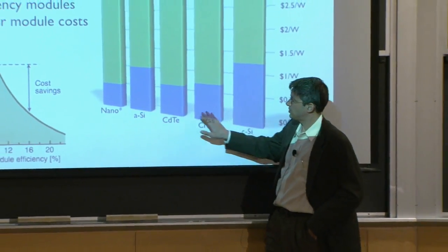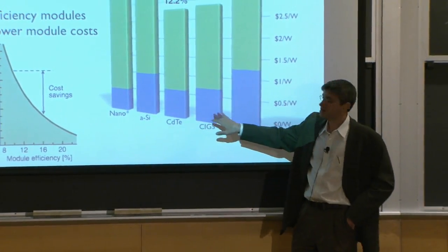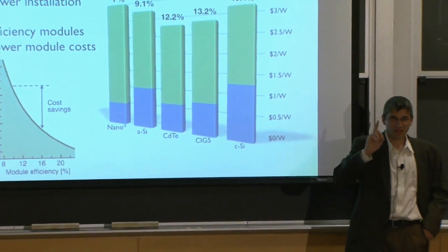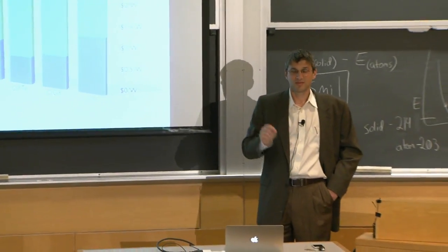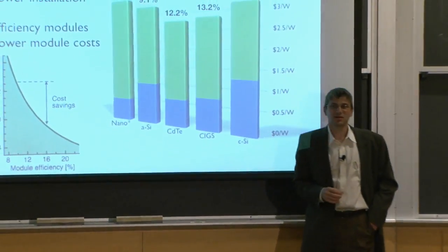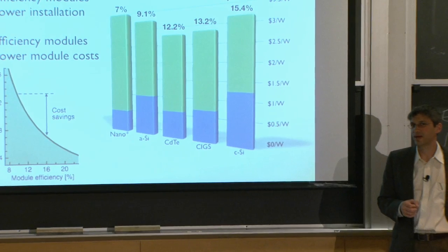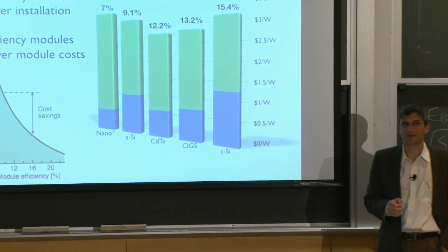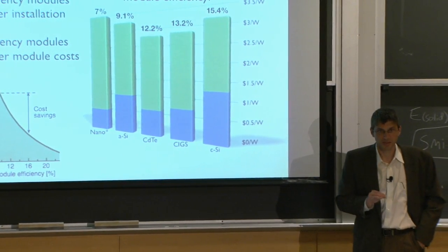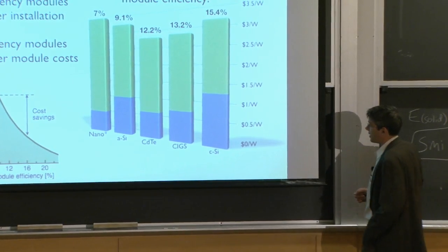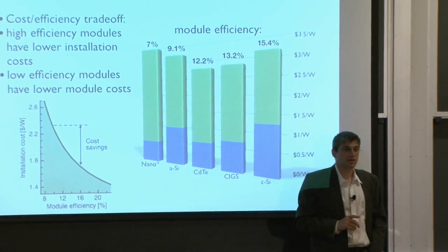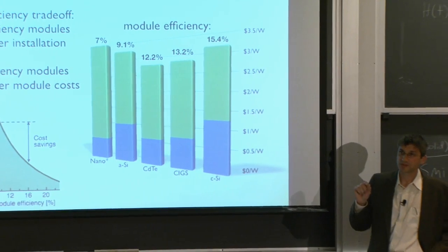So these are all thin film. These are all thin film. This is thick film. Now, what can you compute because of this class to tell me why this is thick and these are thin? Is it the band gap? What about the band gap? Direct or indirect, as a first approximation. Is that band gap direct or indirect? Indirect here, direct here. Therefore, you can make very thin films.